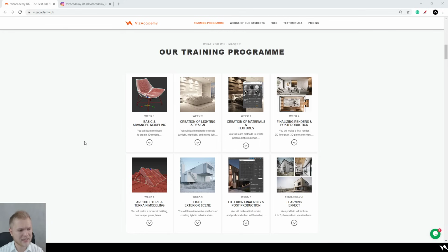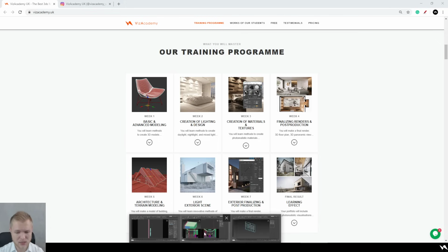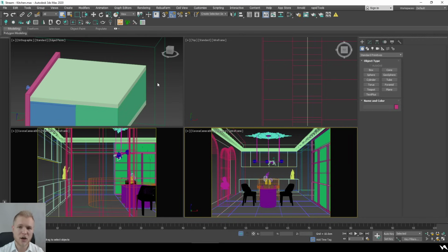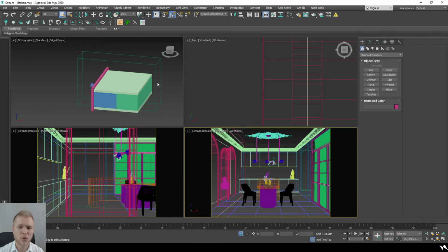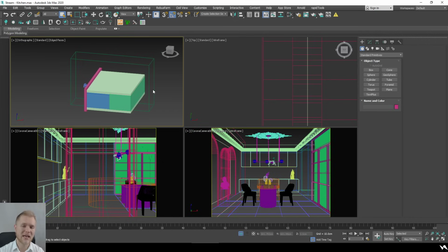To be honest, Gamma 0.1 is an outdated way of working with 3D, and I would actually argue that working with the default Gamma of 2.2 is going to be most efficient for ArchViz, and working with Gamma 0.1 is not going to be necessary in most cases. Why? Because it's just outdated. It may be something that they found to be more comfortable for them, but the spectrum of light is actually going to be on your side when working with Gamma 2.2.